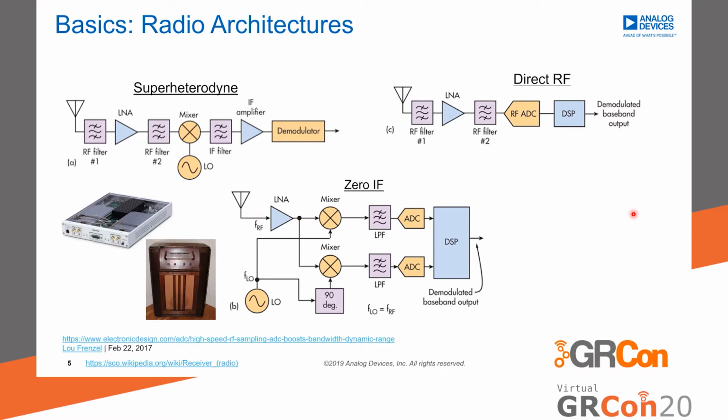These devices are really considered like traditional designs, but modern SDRs, modern radios that people develop still use this architecture. Here on the left, we see just an image of an X310 that has a pair of TwinRXs, which are actually superhet designs, as well as like a super old school kind of radio that you would see probably in your grandfather's basement or something.